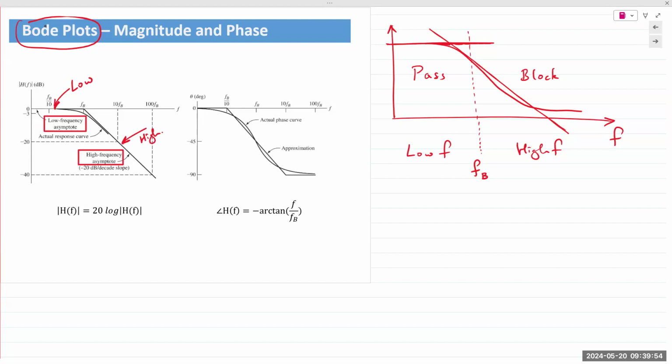And these slopes for a first order filter are always standard. It'll always be 20 dB per decade. The key figure is 20. And we will look into detail what a dB and a decade means. dB and decade are terms that we use to compress our scales, so we can describe a large range of values in a small chart.